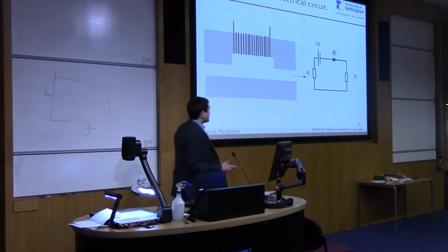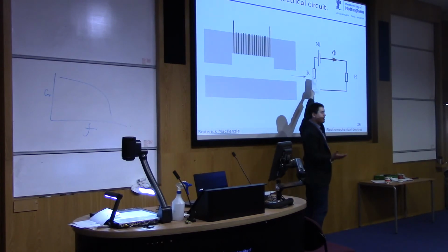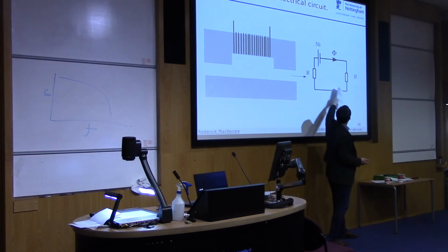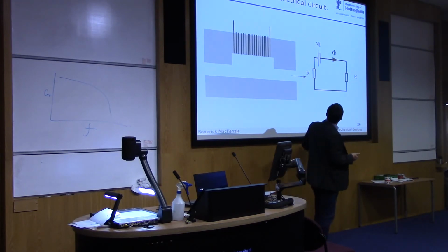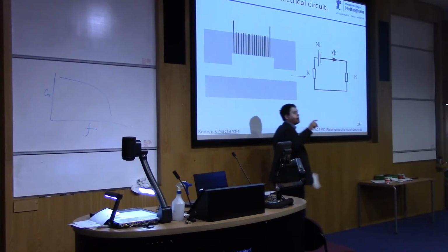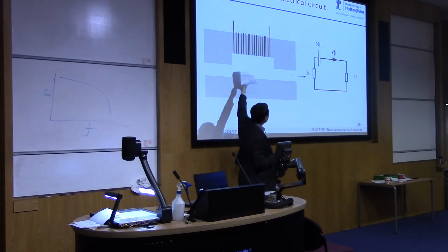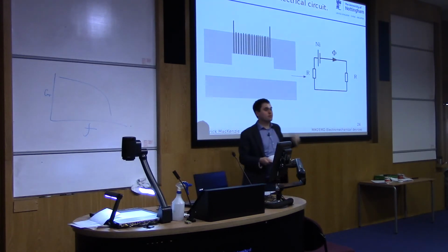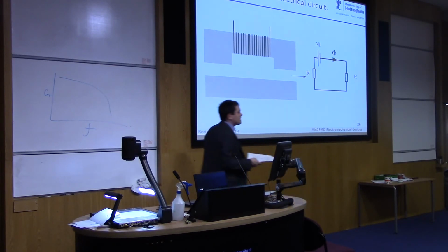And then I label everything just to make me feel even more comfortable. Here's a resistor, give it an R. Here's another resistor, give it another R. And we've got a phi for magnetic flux. And we know, because Arthur's told us, N times I is how much magnetic current the coil is going to generate. I is the current you put into the coil, and N is the number of turns. So the more turns you have, the more flux is generated in the circuit. Everybody happy with that?